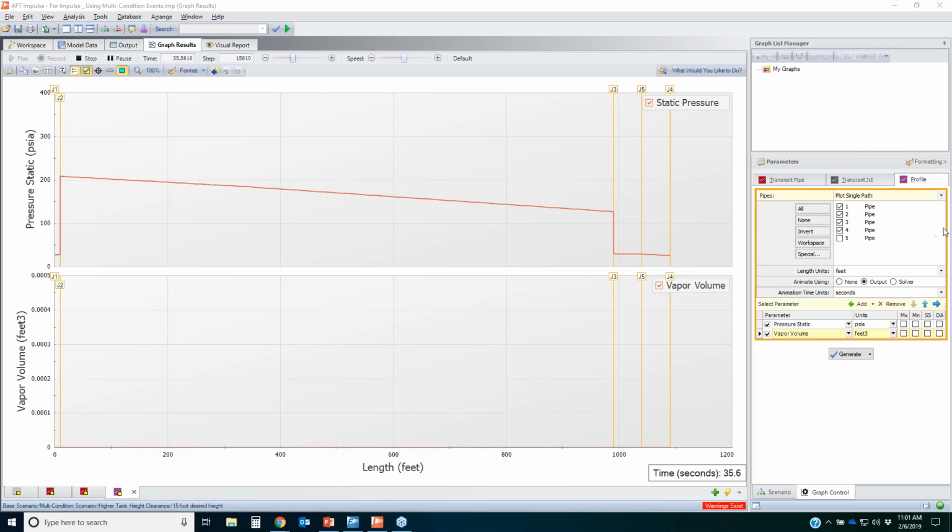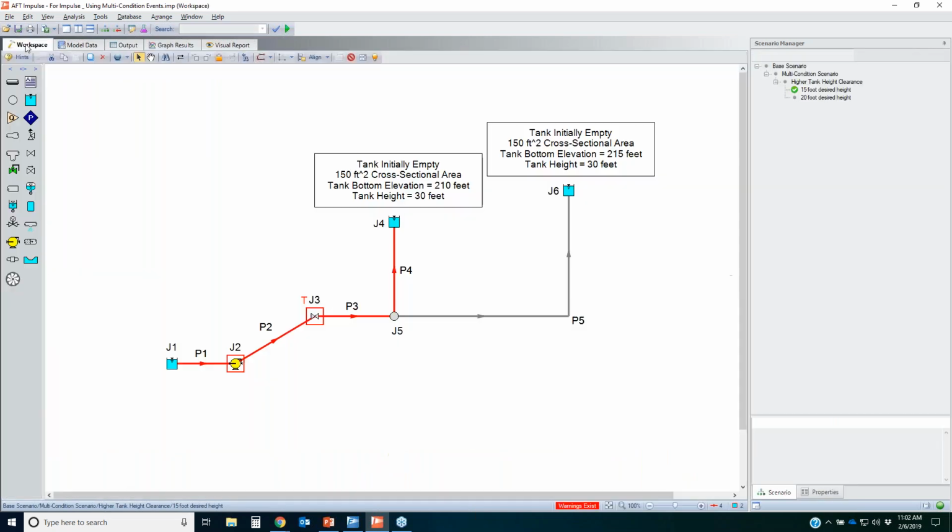But we haven't looked at what's going on over the whole period. And so we need to keep moving forward in time. So now we can start to see how these oscillations are getting larger and larger. The reason why this is happening is because we are deadheading that pump against the closed valve, and the system is just becoming more and more unstable. So this just shows you that you don't want to be operating your pump when you have a closed valve, this is what the system pressure would look like.